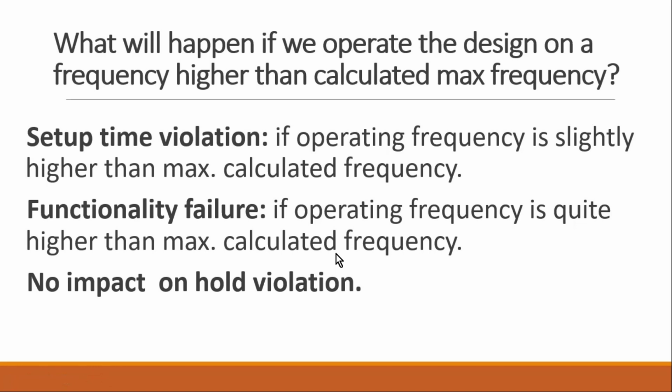And for your information, there will not be any impact on the hold violation because hold time violations are independent of operating frequency. Friends, I have explained whatever I have mentioned in this slide in quite some detail with the help of an example in part 1 of the same series. I will share its link in the description section as well as in the I-bar section. You must go through it.